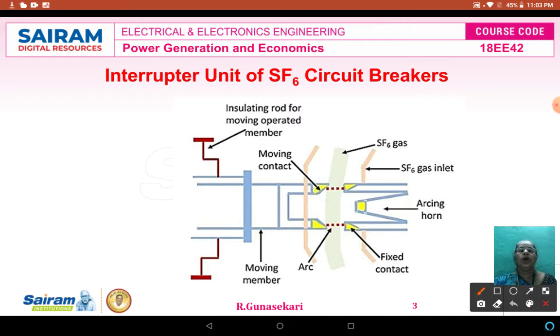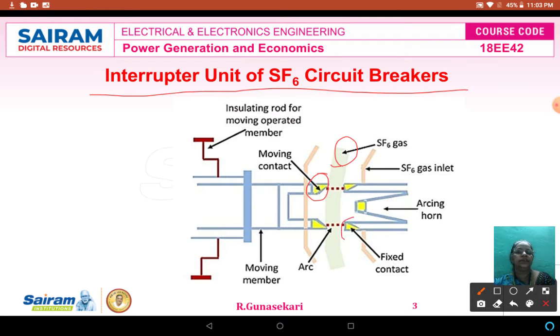Okay, you see how the arc is produced between the moving contact and the fixed contact. So this diagram represents the interrupter unit of the SF6 circuit breaker. From this diagram you can easily understand the working function of the SF6. So this is the SF6 gas. This is the moving contact, and then this is the fixed contact. Then this is the moving chamber.